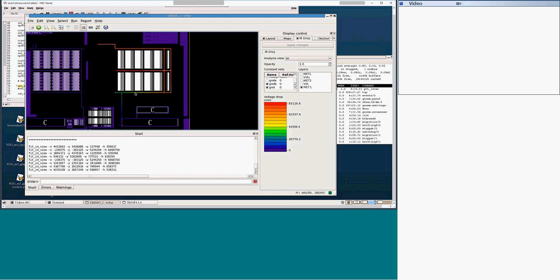You can do IR drop analysis only on metal and cut layers, and in some cases on poly layers, if you include poly layers, but not on diffusion layers. Diffusion layers are like continuous spaces, bulk material. So calculating an IR drop graph in such a distribution is beyond the capacity of the tool. We want well-defined geometries.